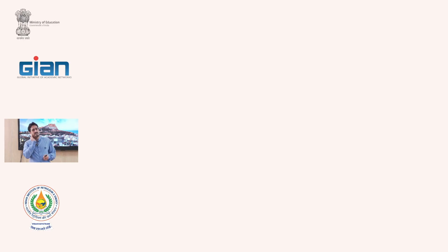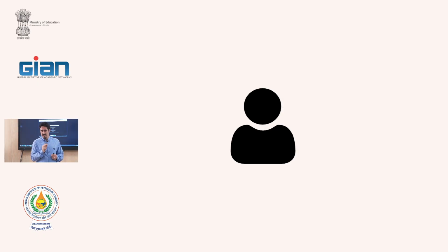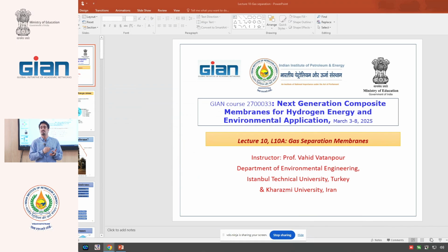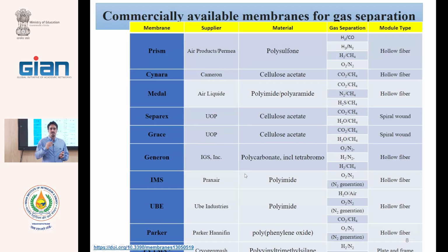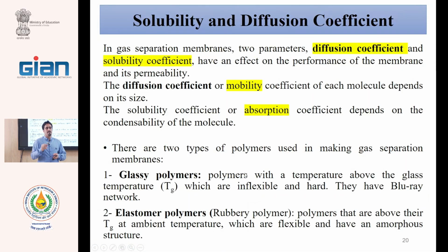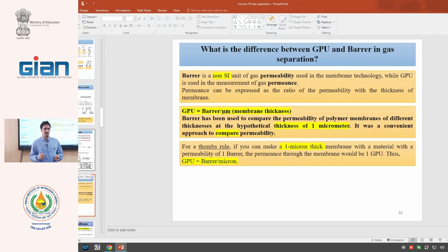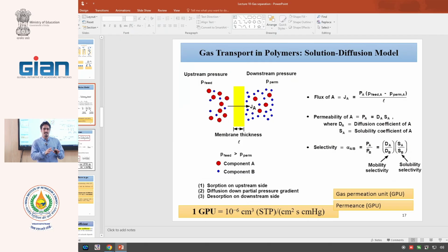But in gas separation, when two students test one gas separation membrane, they cannot report different fluxes or different permeances, because the permeability, the barrier, of each polymer for each gas is constant. And we can find it in the literature. We can find that this PIM has a carbon dioxide permeability of 12 barrer. If you report 13, the paper will be rejected, your data is wrong.